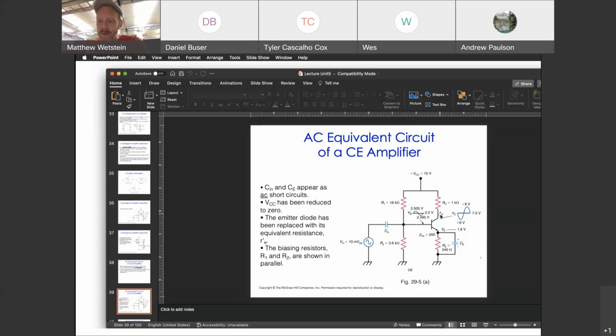And there's also, by the way, if I'm picking this signal off with a DC probe, it's going to have an offset to it. It's going to be a fluctuation around the quiescent voltage of 7.5. But very often when people make these transistor amplifiers, they'll put a capacitor on the output. They'll capacitively couple it, which will give you the same amplified signal, but centered at 0, which is probably what you want. It's still phase shifted, though, in that case.